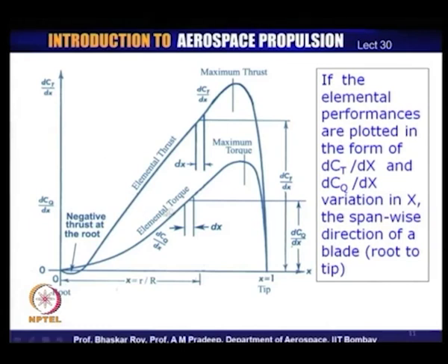So, most of the thrust needs to be created on the outer half of the propeller. However, near the tip of the propeller, again as we can see, the torque and the thrust dip very fast. So, very near the tip of the propeller, the tip flow actually highly influences the propeller elemental behavior there, and you are unlikely to get much thrust contribution from the tip area.